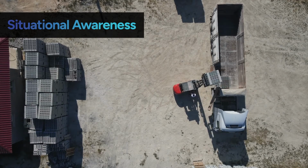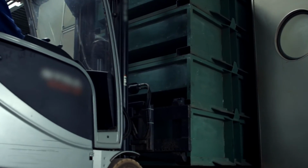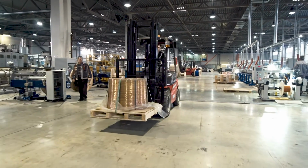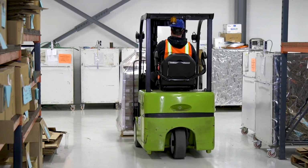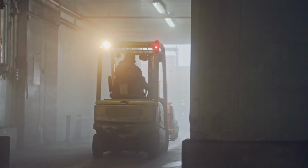Situational awareness is also important because it helps you to avoid sudden corrections, which can destabilize the forklift and lead to safety hazards like tip overs, fallen loads, or collisions. Pay attention to your load's dimensions in order to avoid collisions with overhead structures, objects, and people. Keep a safe distance from walls and other obstacles to minimize sudden movements that could destabilize the forklift. And exercise caution around blind spots like corners and doorways, making sure to slow down and use your horn to let others know that you're there.